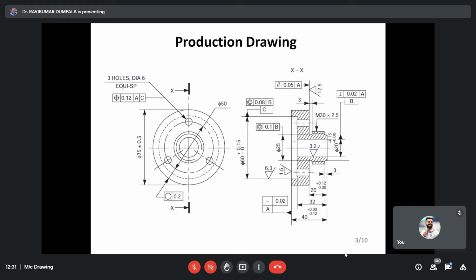You see somewhere they have given the internal diameter. I think if it is critical, yes, here you see, the internal diameter is given on the right side. For the 20 diameter, it is given 0 to 0.15 mm, that is 150 micrometers. Still, it is a big tolerance.